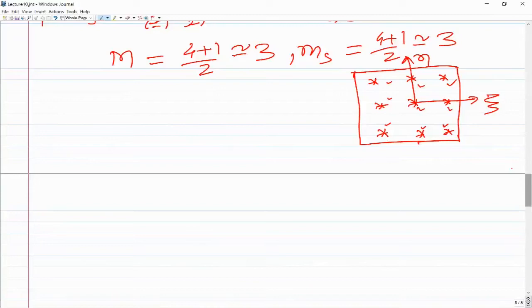It will happen if you are using this element for thin plate problems. Of course we would like to use the same element rather than two different types of element, but then we have to take care of shear locking.